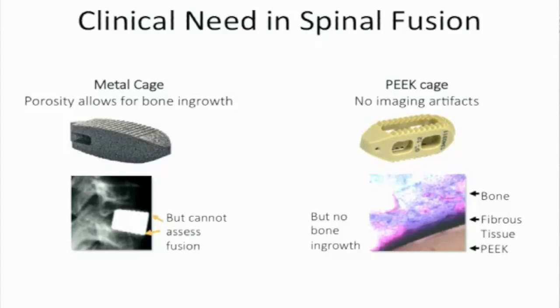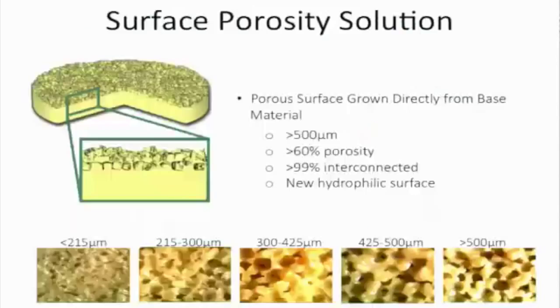So this is where our newest thing comes in. What we figured out is, why don't we do something to the surface of the PEEK to make it stick to the bone better? It's an obvious thing, but the answer is hard to get to. Then we don't have to have the metal, and we can have it stick. We first tried all kinds of stuff. Let's just coat something on there. Let's just sinter some particles, because artificial hips for many years have had titanium beads sintered on them. We did, and the problem we faced was the PEEK was not taking any of that stuff.